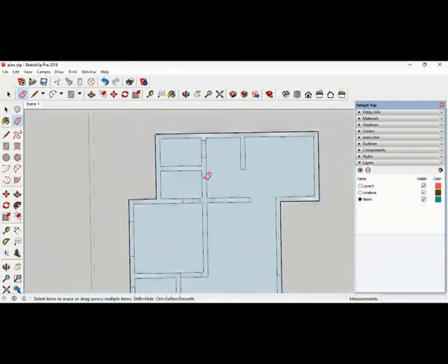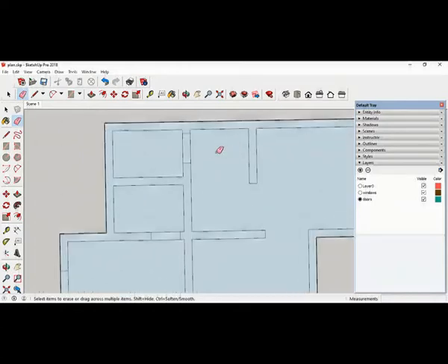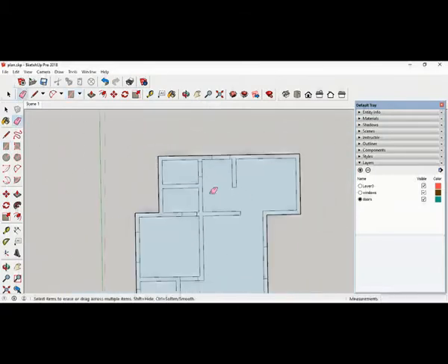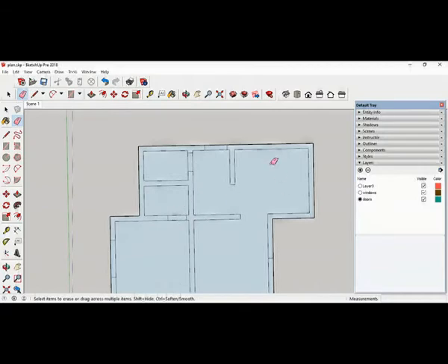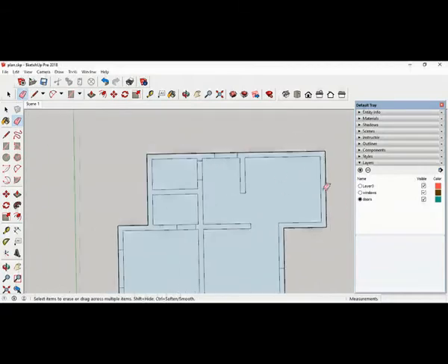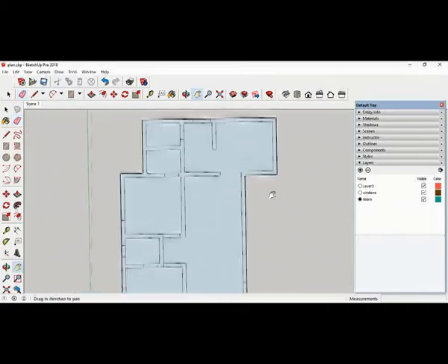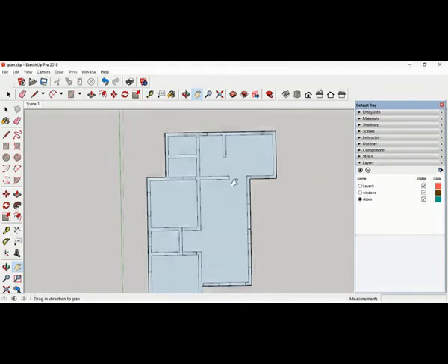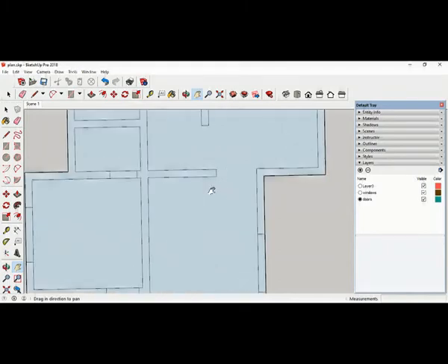Okay, so there's entrance here. There is a door here. Tape measure tool T, 0.1, 0.9, rectangle, erase. That's all. Okay, and here two windows are coming. You can draw that. There is one window coming here. So we have drawn window here, door. So this door we have to check whether it is correct or not.